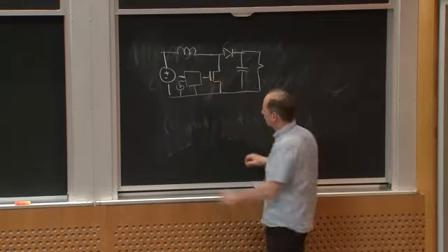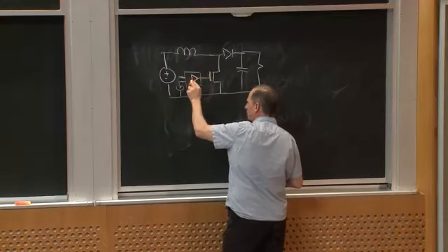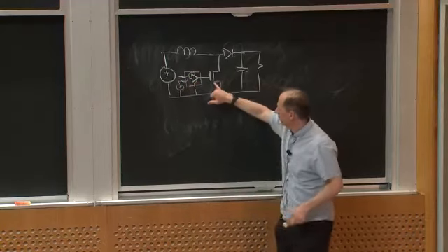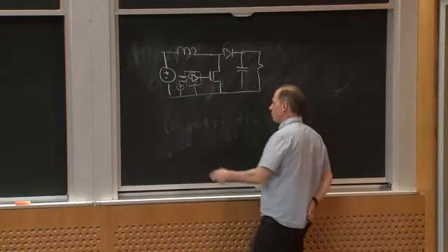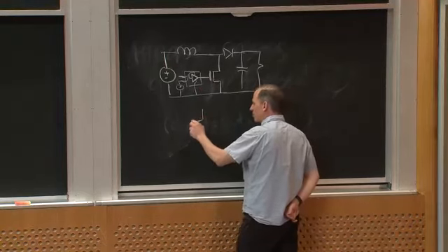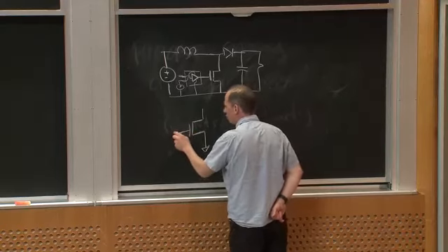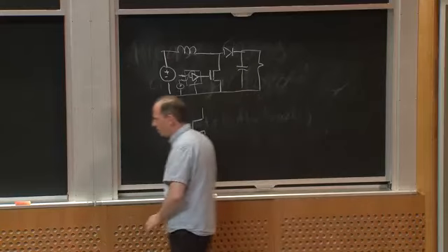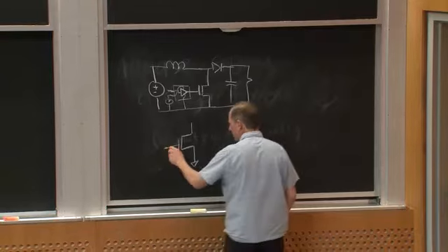Well, the last thing between me and my switch is some sort of gate driver, right, which is going to be powered from some voltage, and he's got some signal coming in, and he's going to try to turn this transistor on and off, right? So if I thought about my transistor, here I'm going to drive this with some square wave voltage, and I need to remember that this transistor is going to have some gate source capacitance.